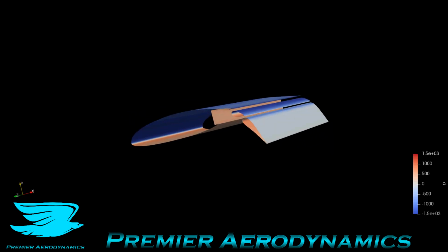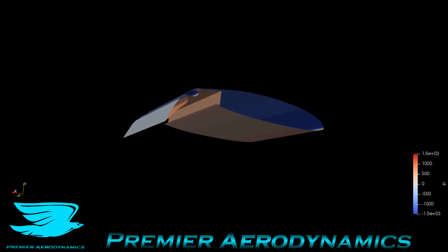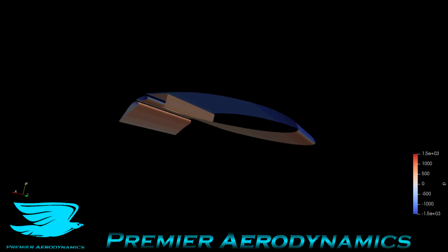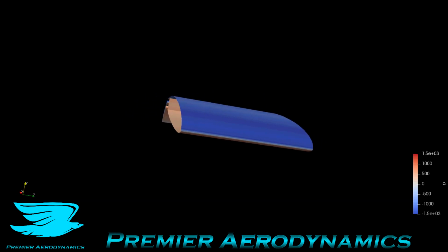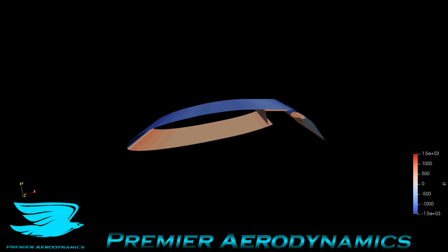And you can get even higher, you can get to 3.4 and even higher if you really design the system very well. But as you can tell, it's very far above the average lift coefficient of an airfoil of like 1.2, 1.5, 1.8. So that's it in the simulation.